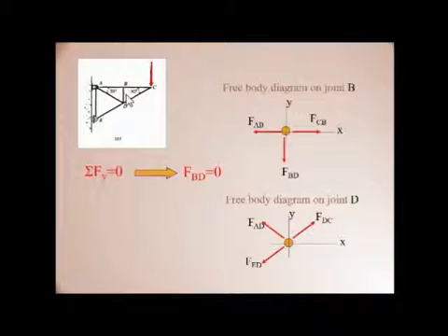Acting on this point, joint P, we also can get FBD equals 0. Now again progressing with another point, that is joint D. First of all, we'll start with such a point where fewer variables or unknowns are there. Then we'll progress towards the main truss or the supports. Now by calculating the free body diagram at joint D also, we'll find FAD equals 0, and so on.